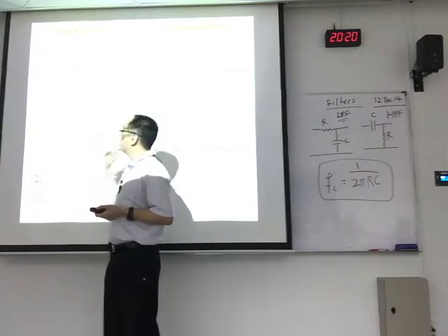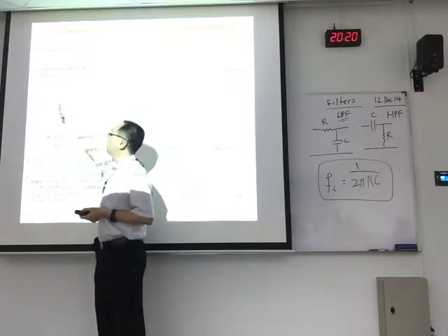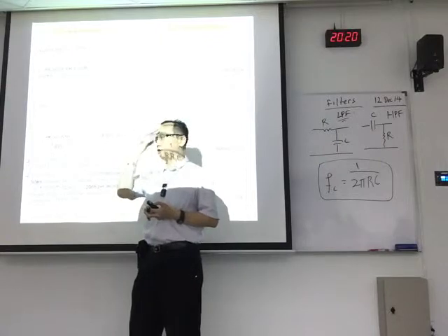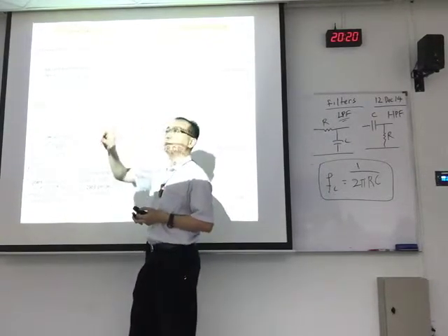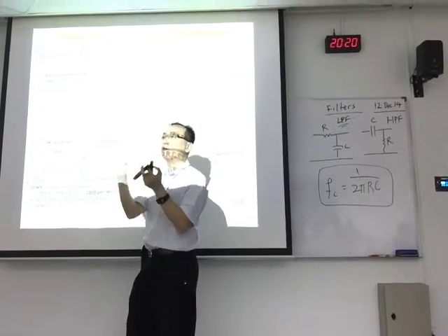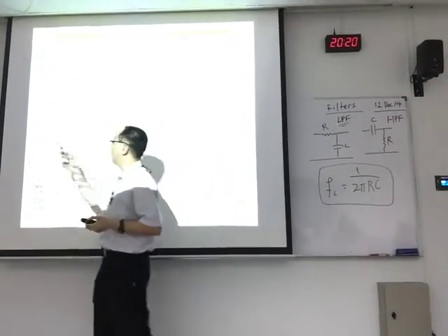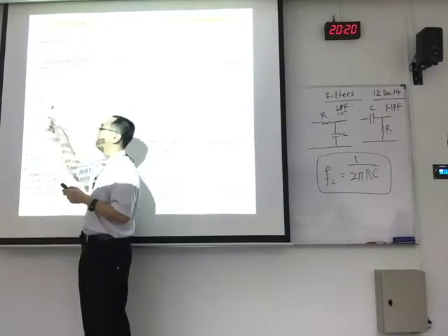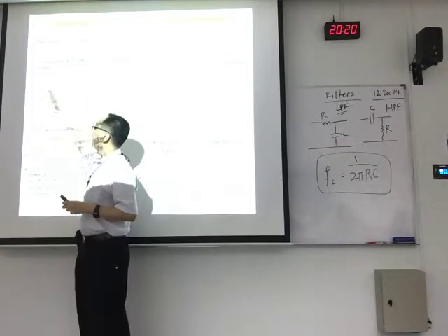Okay, first order filter. So for example, this is the case of a low pass filter. Now I think it's very important you try to remember the precise configuration. Just remember one will do, because don't get confused by memorizing both. It doesn't make sense. Just remember one. If you want to remember low pass, you just take it that I need the R here and the C here. This will be a low pass.